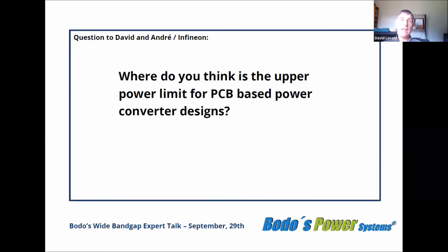I think we see more and more in industry a trend towards going to PCB-based designs rather than the traditional bus bar and screw designs that we've had in the past. I think this is for a couple of reasons. One is with silicon carbide, using a PCB, we can make lower inductance.